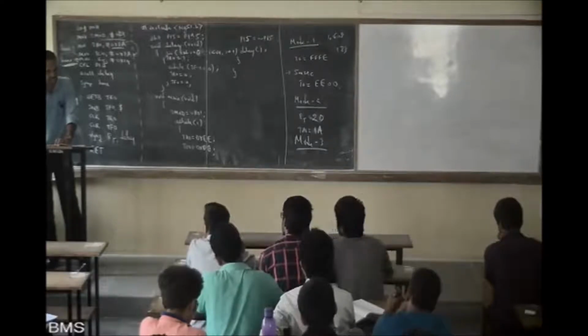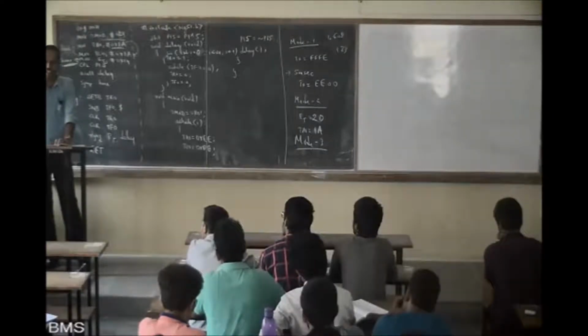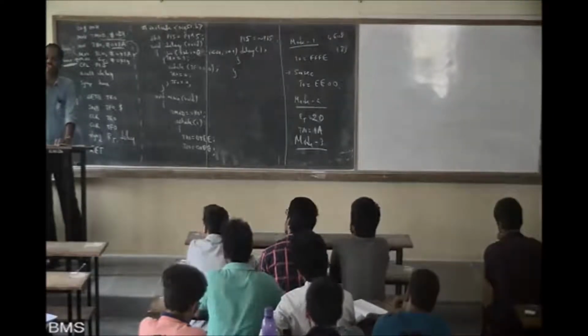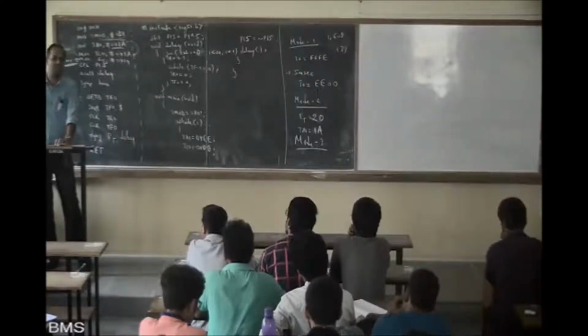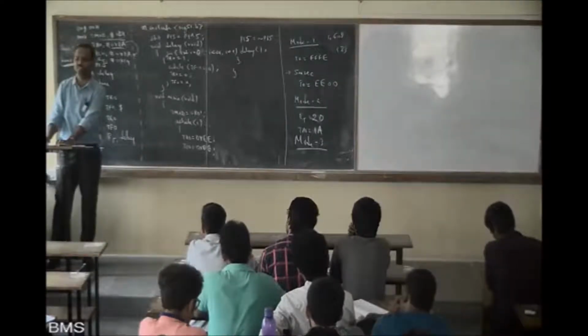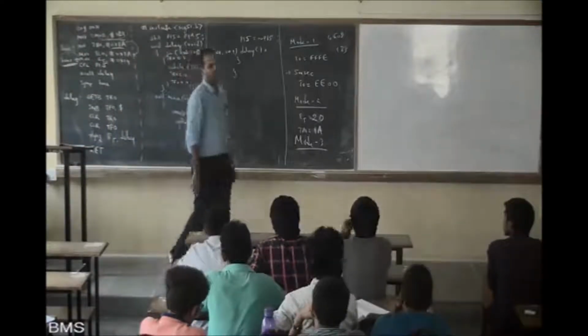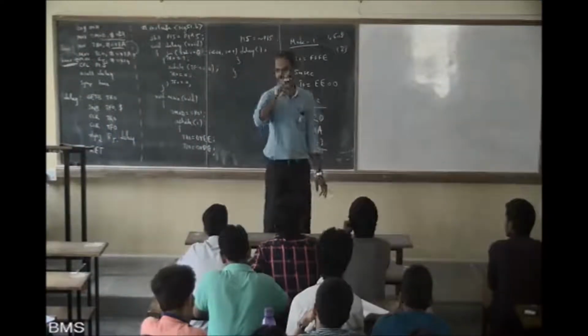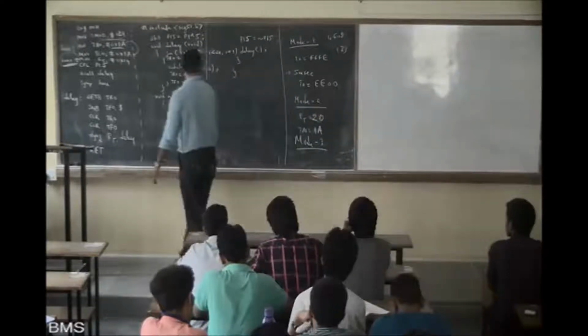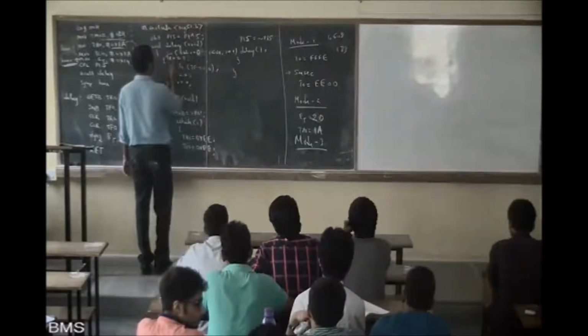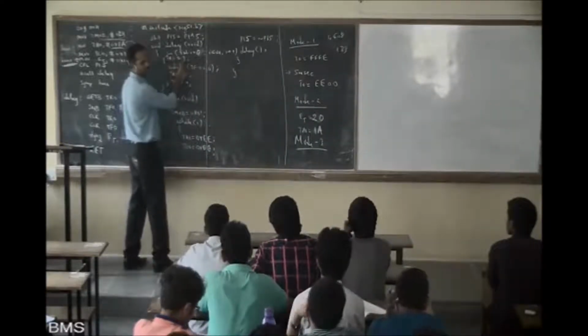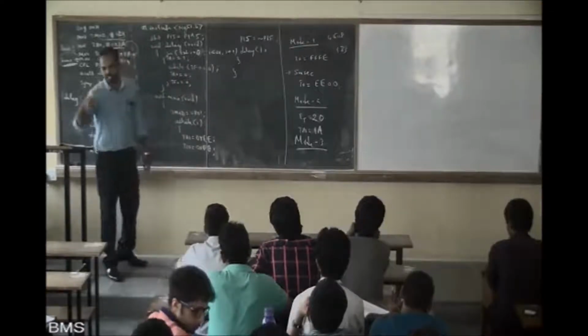In such a case, guys, listen. There is no meaning of TR1 for timer 1, but there is a meaning of TR1 for TH0. If you make TR1 equal to 1, then TH0 will start.